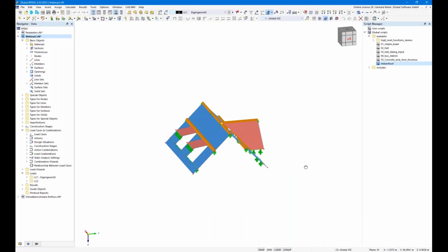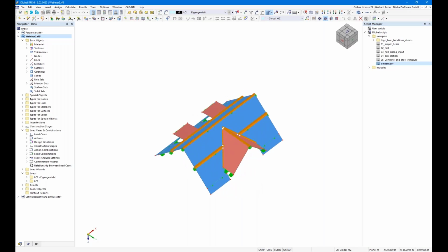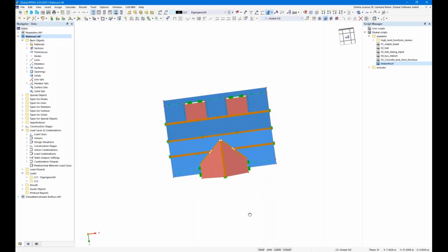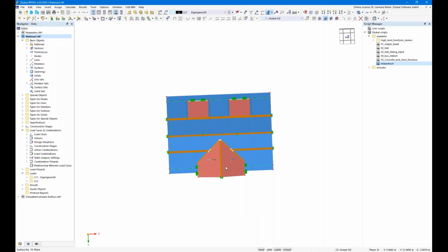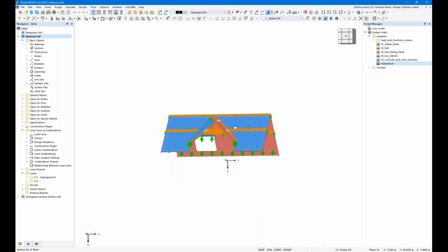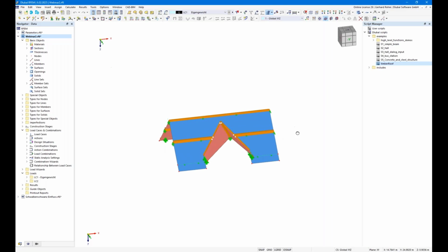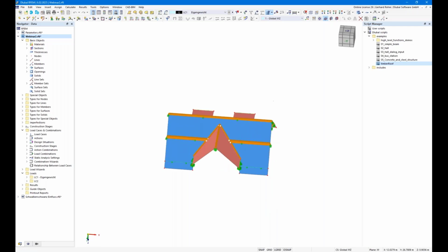And the question is always how to get the loads on it easily. Is it on the safe side to design the purlin with a whole load from this rafter, for example, or maybe when this building here is taller, then of course maybe this is design giving, because this gives you a nodal load here, or it gives you a nodal load here in the purlin in the center. So that's always hard to get a good approximation.